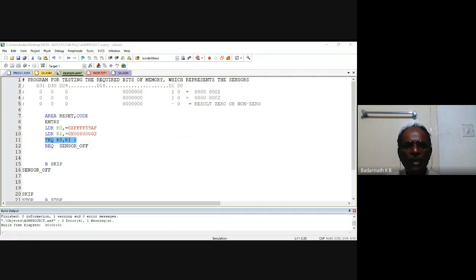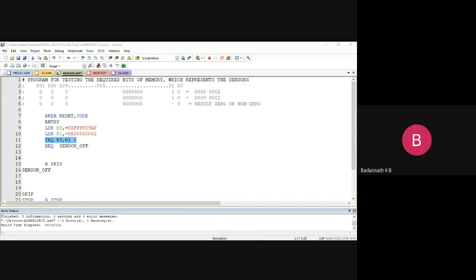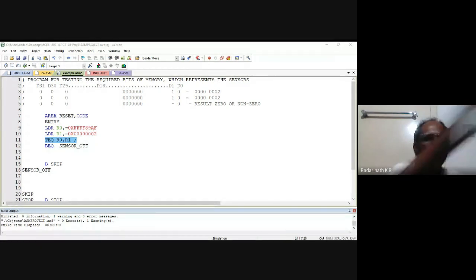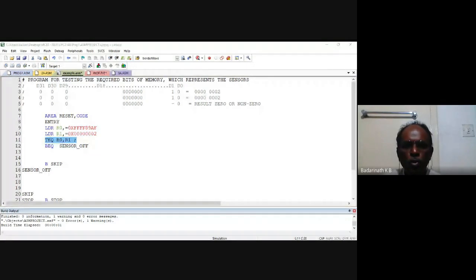So this completes all the instructions which are used for bit manipulation. What are the pseudo instructions we studied? Compare, test equal, and test are the pseudo instructions. There is one more, reverse comparison. Instead of R1 minus R2, you can do R2 minus R1. That is also a pseudo operation. So basically there are 4 instructions available performing pseudo operations. They are used to affect the flags, and based on that we perform branching.